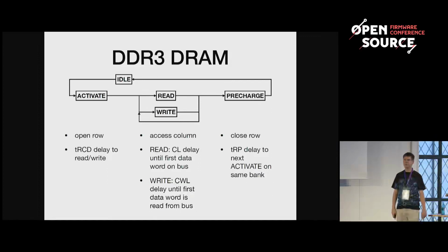That's the tRCD delay for DDR3 and 4. It's in memory clocks and not in absolute units. So basically, when you look at a data sheet from DDR2 memory and at a data sheet of DDR4 memory, it seems that the latency got worse, but it didn't get worse because the frequency increased, and with that also the numbers increased. But the absolute value didn't change that much.